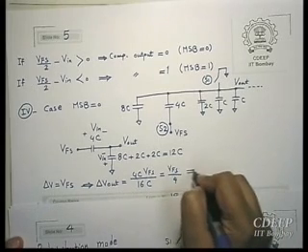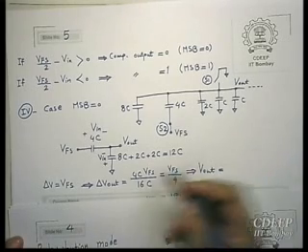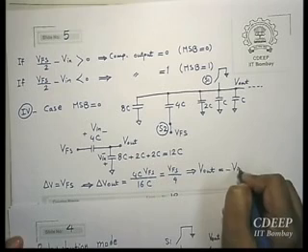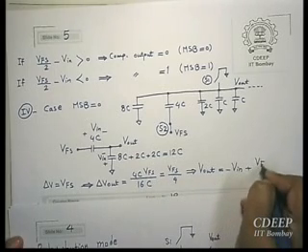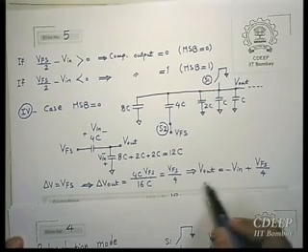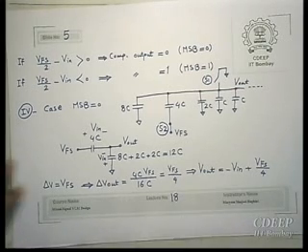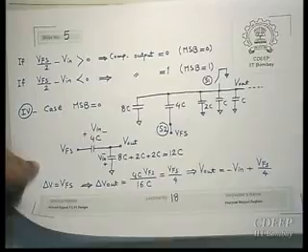Therefore, V out is equal to minus V in, the original value, plus V full scale by 4. It means that if MSB is 0, now we need to compare it with V full scale by 4. And therefore, now again it will continue the same way. And the other case, which was MSB equal to 1, we cover it now.